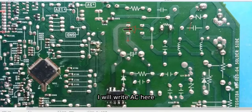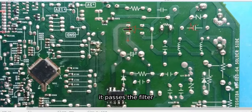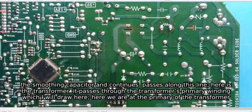I will write AC here. That 220V is input here. Here you connect to the 2 little legs. It passes the filter. Where we work on it, it goes in series. This resistor here, which was burnt, and this one I showed you before. It passes through the bridge. You rectify. The positive goes to the smoothing capacitor and continues, passes along this line.